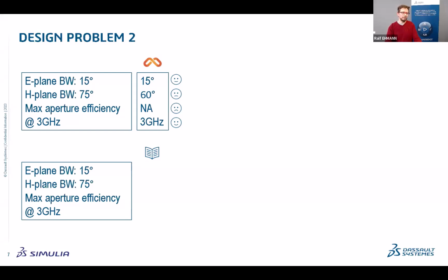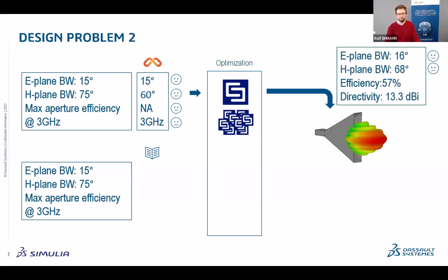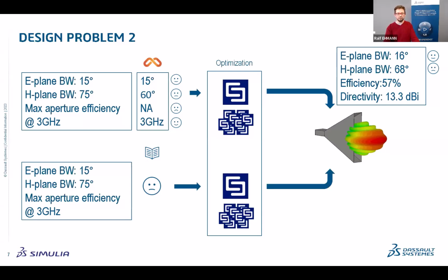So the next step would be then to do the design as close as possible, export to CST, and then do an optimization. Now this might not necessarily give you what you want. You might be closer, or you could go the conventional method again. I doubt whether there's an explicit design for these objectives out in the literature. You'd also have to optimize, get the same results, and this might also take an hour or more, maybe days.